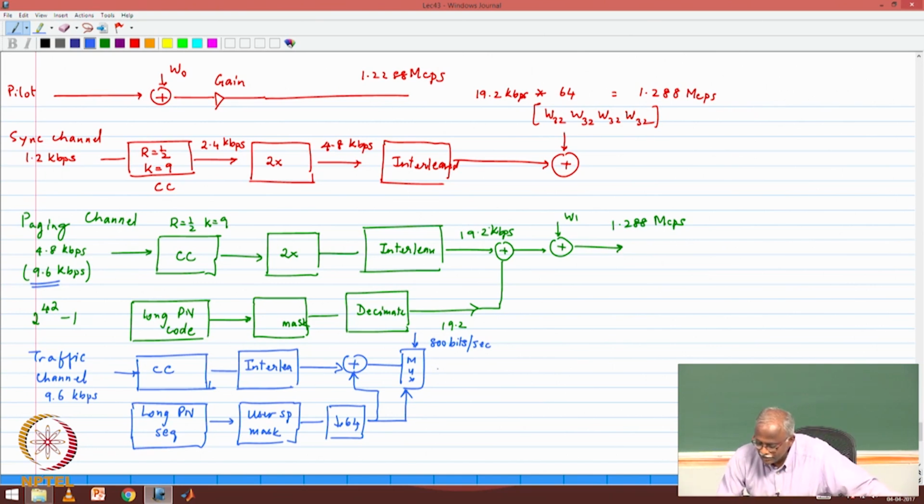And this information is then spread by, well, if you're doing it in binary, it's a plus sign. Okay, basically it's a spreading sequence, Wj. This can be any of the spreading sequences that are done, and of course this is the output. Now what is it that you punctured in and what did you insert? This is what we call the power control bits.